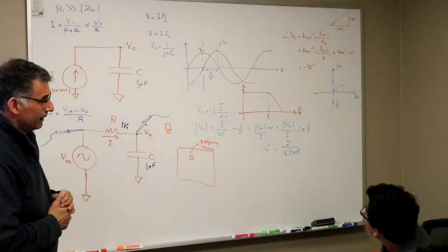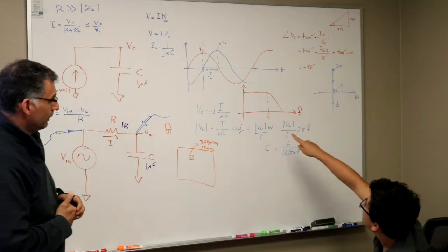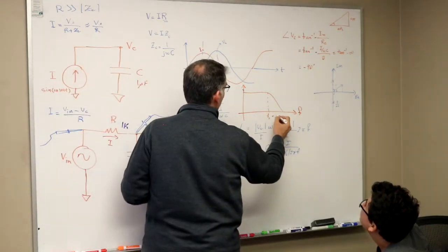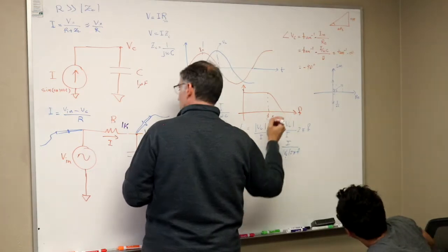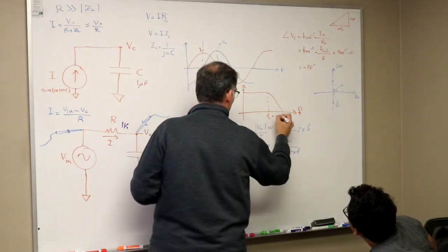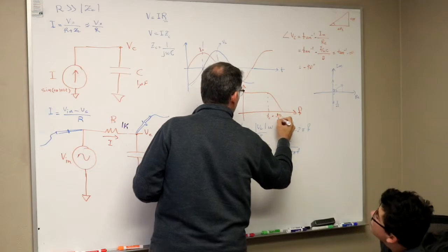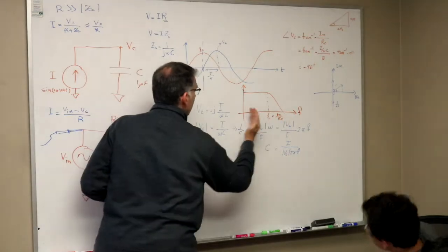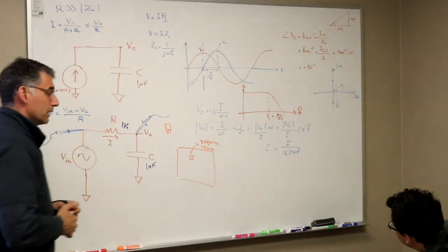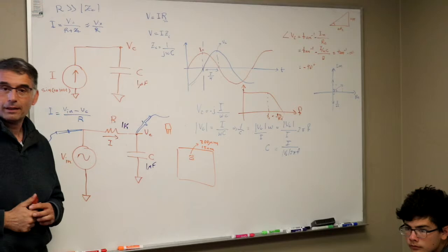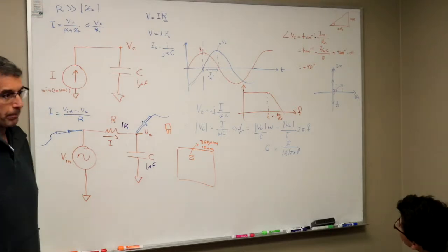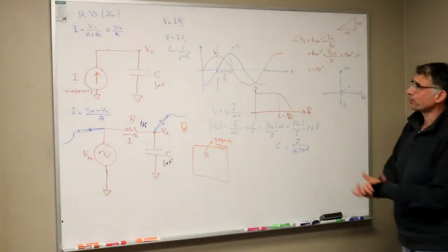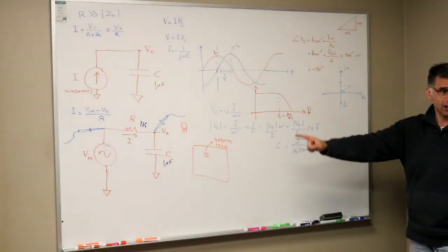If you want to cut out the higher frequency, you figure out what this value is, and this value is actually 1 over 2 pi RC. So using that, by changing these values, you can make the frequency higher or lower. This is called a low-pass filter. It's called a low-pass filter, use it all the time. All right, guys, so any other questions on this?